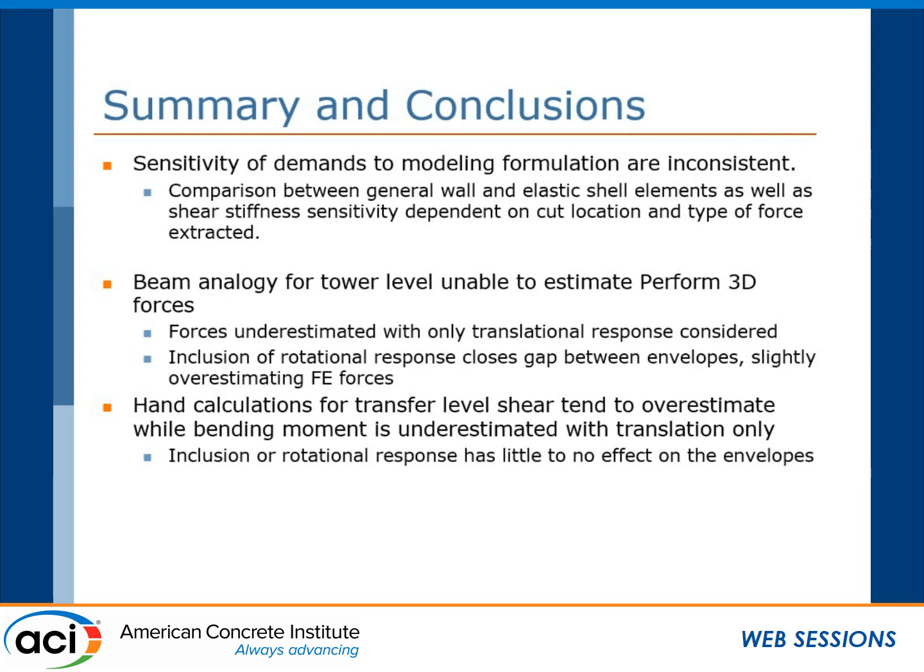And then from the drag force, you saw that for modeling between nonlinear and linear, the compression drag tends to get higher when you model the diaphragm as linear, but the tension drag is higher when you model it as nonlinear. And then for the beam analogy, when you try to estimate the diaphragm forces by assuming it as a rigid beam, the beam analogy is better estimated when you include torsion rather than if you just use translational forces.